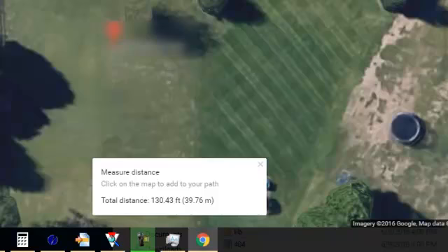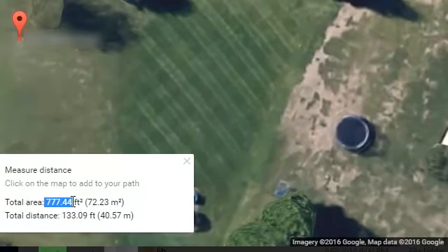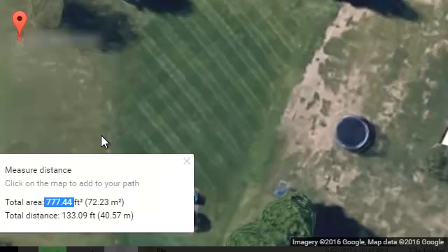To keep everything in order, I take an aerial picture of all the roof from all angles and copy that into a Word document. Then place the measurements of each surface on that picture to later total them up. This helps let you know where you are on the measurements, especially if you can't finish it right away.